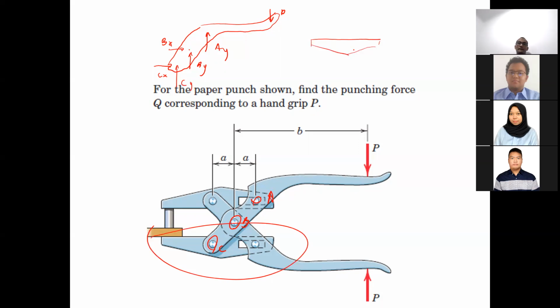Okay, what forces do we have there? CX and CY. If CX and CY are going up and right in this particular free body diagram, how are we supposed to draw it? Okay, Raditya? Down and left. Okay, correct. Down, CY, and left, CX.